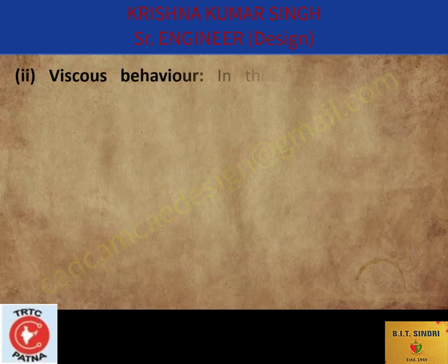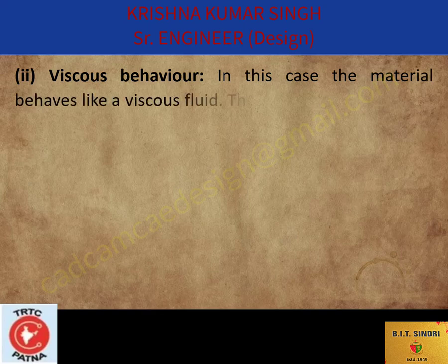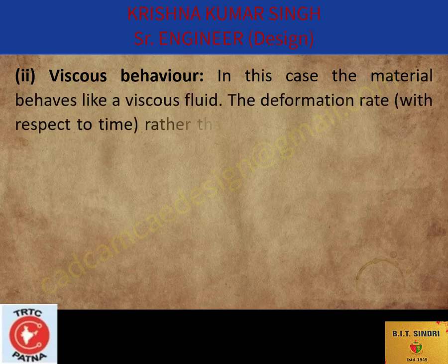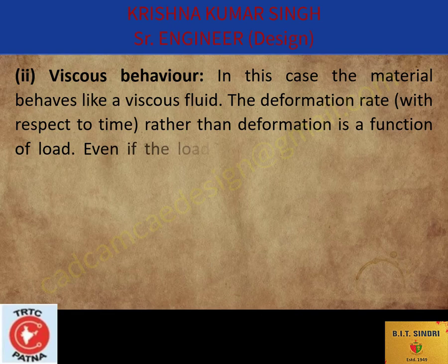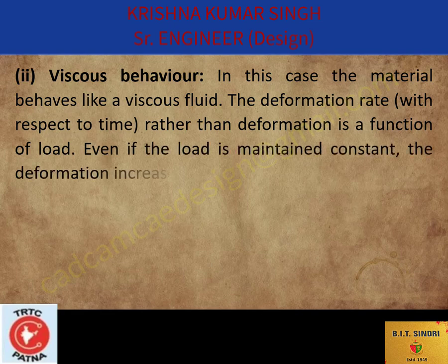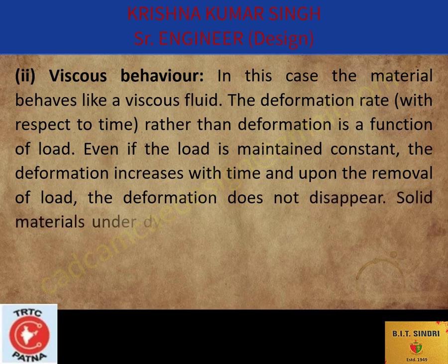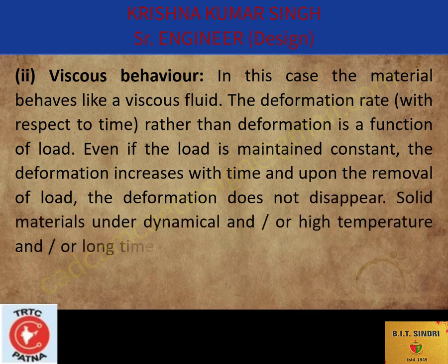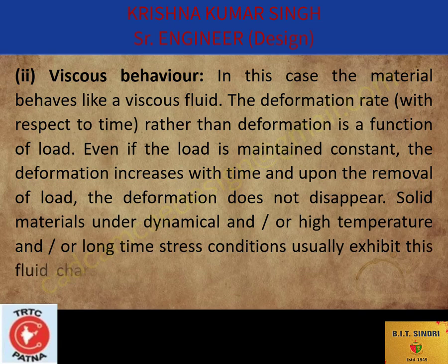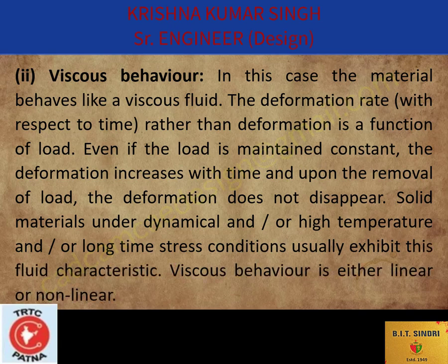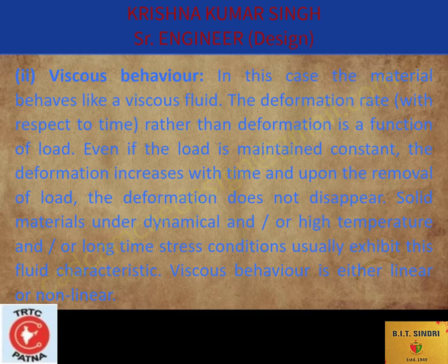The second point is viscous behavior. In this case, the material behaves like a viscous fluid. The deformation rate with respect to time, rather than the deformation, is a function of load. Even if the load is maintained constant, the deformation increases with time, and upon the removal of load the deformation does not disappear. Solid materials under dynamic and/or high temperature and/or long-time stress conditions usually exhibit this fluid characteristic. Viscous behavior is either linear or non-linear.